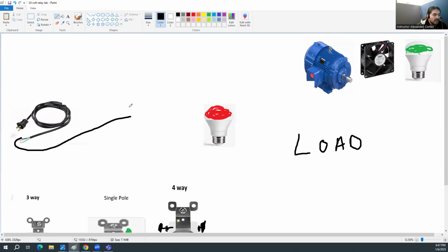If you were to grab this power cord and plug it in, the black wire would be where the electricity would start. That's your hot wire. If you were to connect that black wire to the brass terminal on a light base and just have the hot wire plugged into your light, electricity won't flow, because it needs a closed loop, like I mentioned earlier.